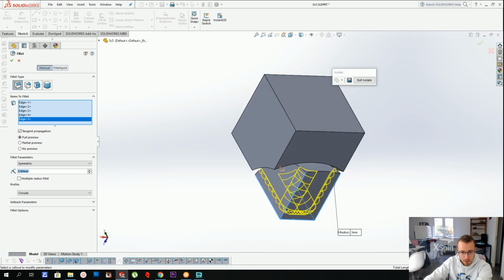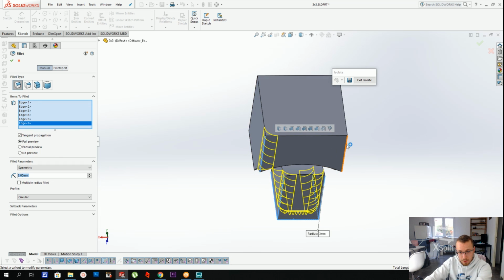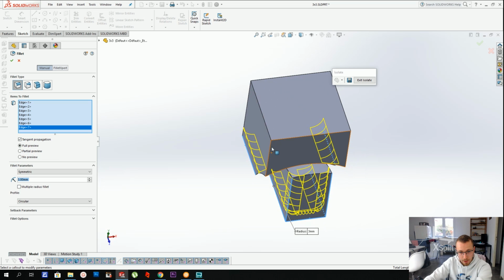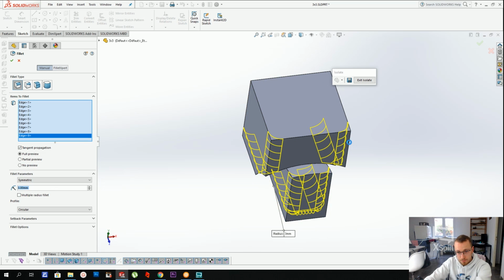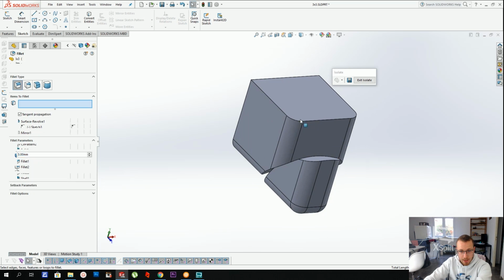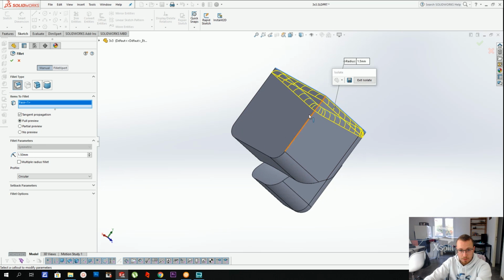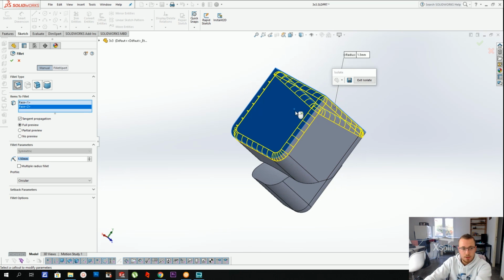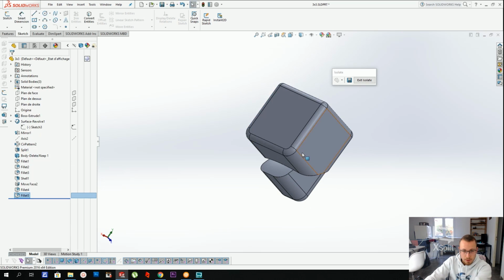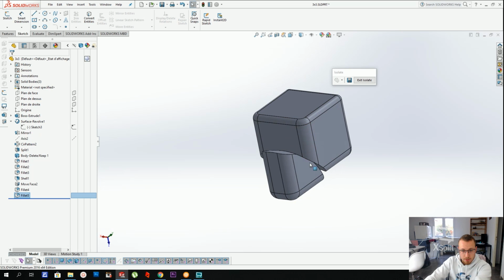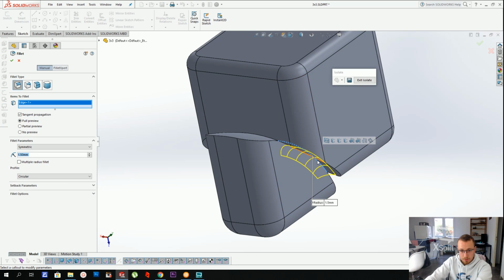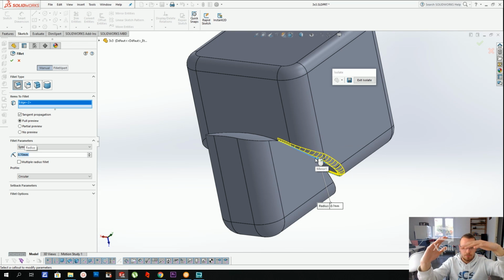Right there. And here you've got corner cutting edges as well, so we're going to add some pretty big fillets there too. Once that is done, we're going to add the top face, the sort of visual fillets. So 1.5, and now the functional fillets on the inside that are just to avoid parts catching between different positions on the mechanism, so different layers on the mechanism.